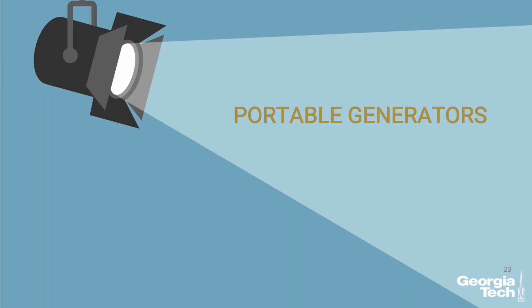Portable generators are internal combustion engines used to generate electricity. Portable generators can be dangerous if used incorrectly. Fires from improperly refueling the generator or inappropriately storing fuel are a main hazard associated with the use of portable generators. Portable generators can cause shocks and electrocution from improper use of power or accidentally energizing other electrical systems. Carbon monoxide from a generator's exhaust can be a major health hazard.